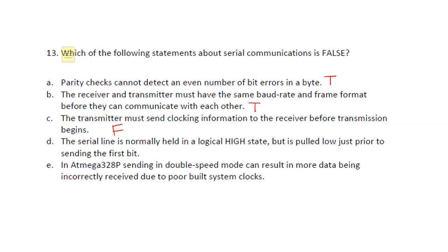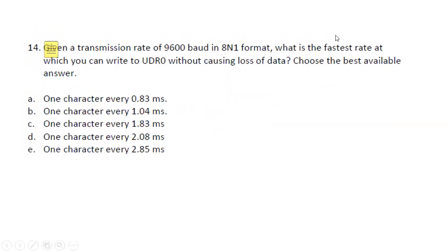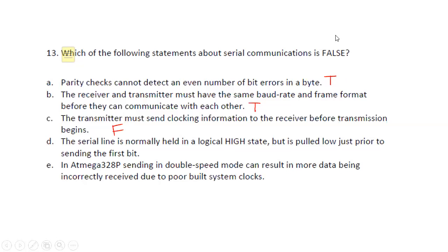If I have a communication protocol in place, with the TX and RX, and I receive and say this is an error, then I can ask for a resend of the last data and see whether it's okay. So that is what you can do at the protocol side, but the UART itself cannot correct any error.